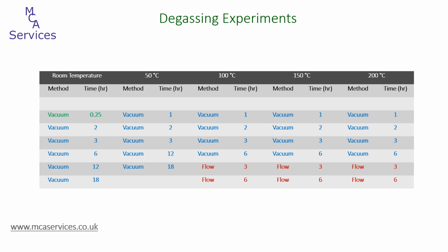It's really useful that the vat prep degassing unit has a vacuum gauge, and this enabled us to stop the degassing of this sample just below the vacuum level that's applied by the TriStar instrument. This is typically a pressure of 1 millimeter mercury, and using the vat prep unit we found that this took about 15 minutes to achieve.